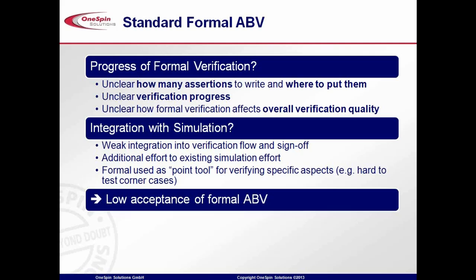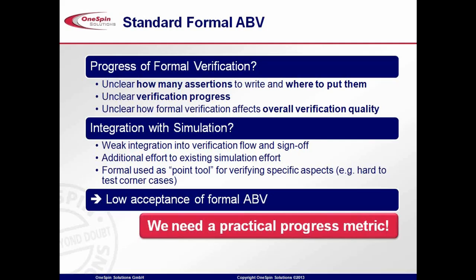For that reason, there is really a weak integration at the moment, and you usually need to have some additional effort. Due to that, formal tools are used as a point tool or for the purpose of finding only the corner cases. And that's one of the main reasons almost for the low acceptance of formal assertion-based verification. And then we really need a practical way to resolve this issue.